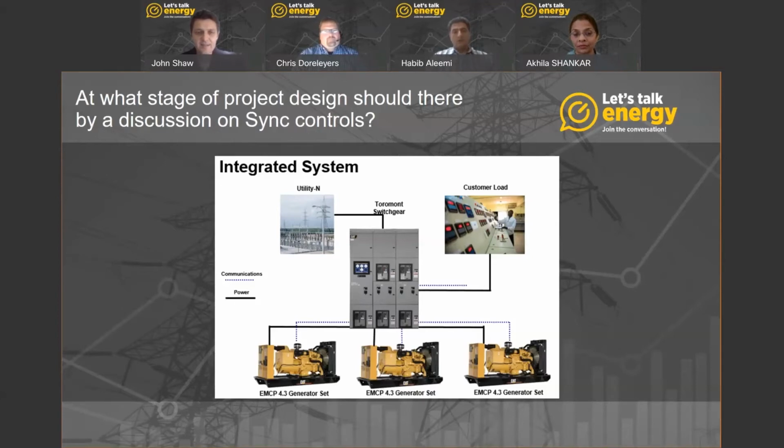Sure, John. Redundant PLC is used in the system to minimize the single point of failure, increase the reliability of the system, and keep equipment and people safe. The control engineer should consider if a continuous process is required or how critical the industry is when choosing redundant PLC. Based on the site requirement, we can choose the level of redundancy. For example, if redundant CPU with non-redundant I/O is required, or redundant CPU with redundant I/O is required in the system.